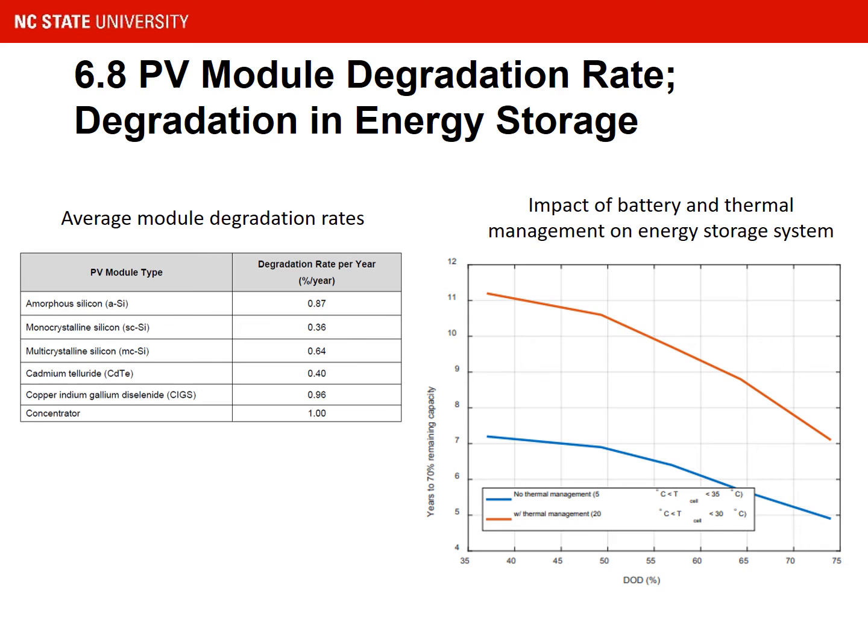One item that I found interesting is that as modules degrade, they do so at varying rates. This causes an induced circuit level mismatch loss that should be modeled in simulations. This could cause complications in maintenance.